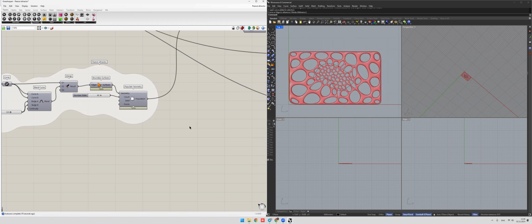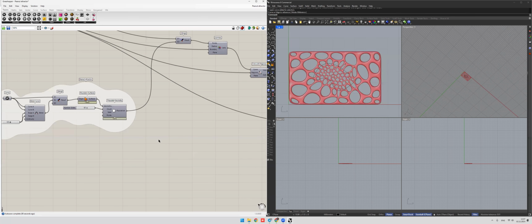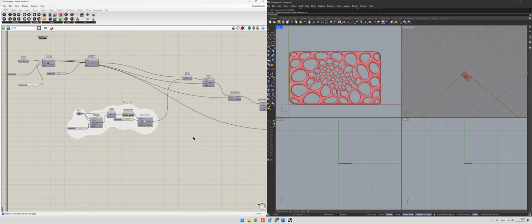And if we use this lattice for compliant joints to make elastic deformation of this thing in a perpendicular way, this dense part will increase the stiffness of the compliant joint. And the idea is, by playing with the geometry of this lattice, to vary the compliance of this bendy thing.